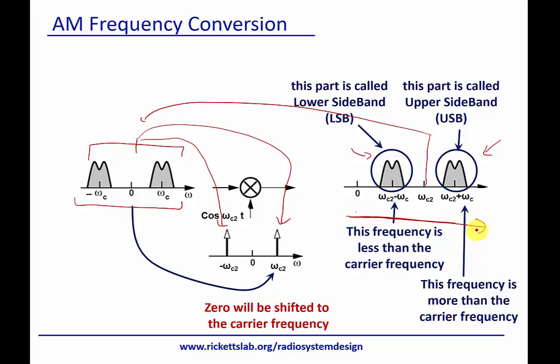So if you're wondering why am I showing this, it's because this piece that for the original signal was the negative side, the e to the minus j omega t, was the image, if you will, of our signal here that's required for it to be real. When we do the multiplication, that actually gets up converted into the positive frequency space.